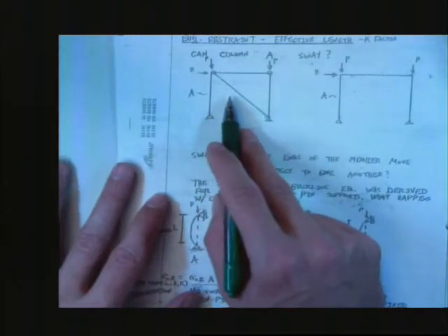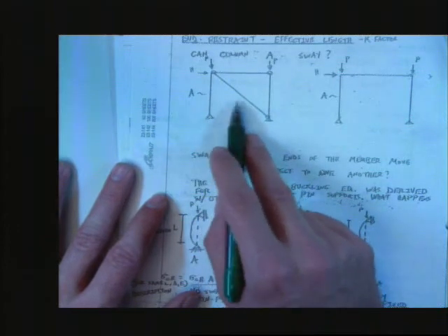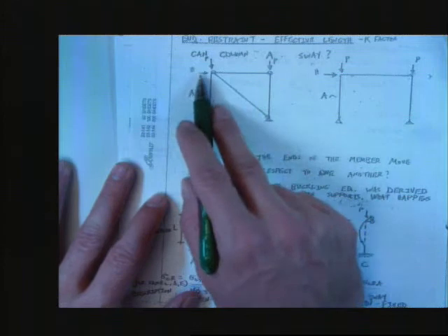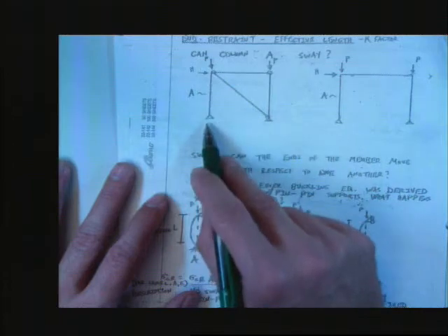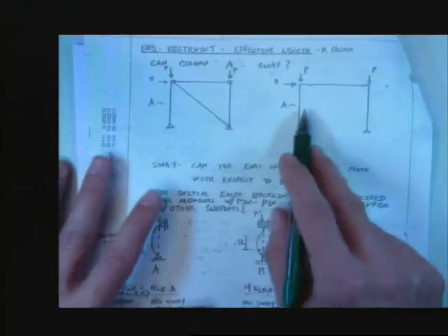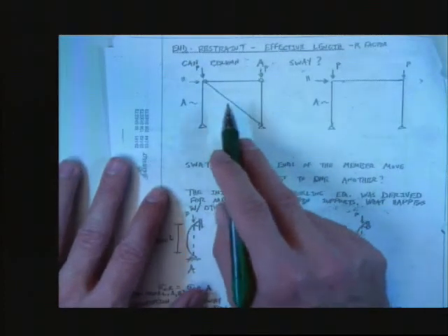So in this column, whenever we draw a brace in this class, we assume the brace is infinitely stiff. In this case, if we have an infinitely stiff brace here, then as we load it, it's not going to compress, so the top will not move with respect to the bottom. AISC actually requires brace design to meet these criteria.